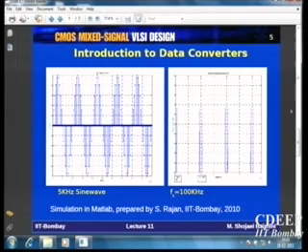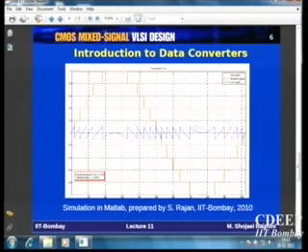Of course, this is the discrete Fourier transform in MATLAB. It shows you the main harmonics of the signal. Here, the only visible component is this 5 kilohertz because there is no other component. It will show you this 100 kilohertz in between, and then plus and minus 5 kilohertz. This is something that you know from switched capacitor theory.